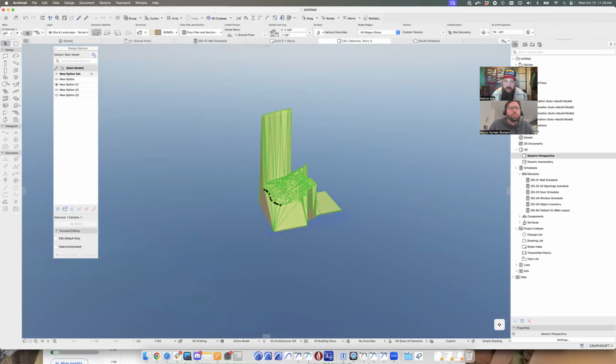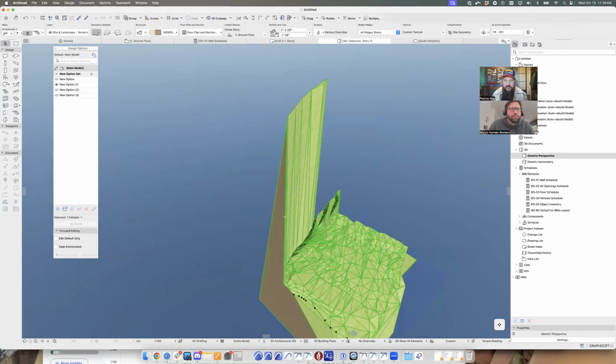And that's another thing: you can fine tune this directly in 3D, the same as I was doing in a floor plan. So I can isolate this contour out. Notice there are no other contours here. And I can either drag that down or I can elevate negative 200 feet.